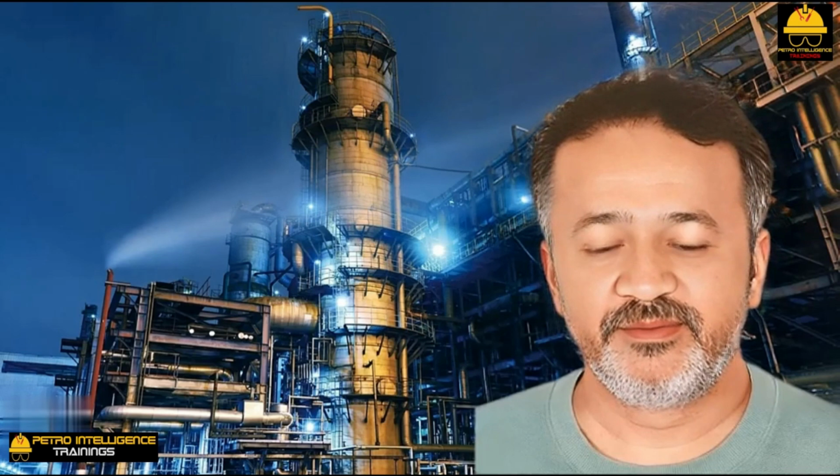In refinery steam condensation services, in both reboilers and steam turbines exhausting to vacuum surface condensers, I have observed that small amounts of non-condensibles greatly reduce the apparent heat transfer coefficient. In reboilers, propane or butane may leak into the lower pressure steam side of the reboiler. In surface condensers, air could be drawn into the condenser's shell, which operates under vacuum conditions.